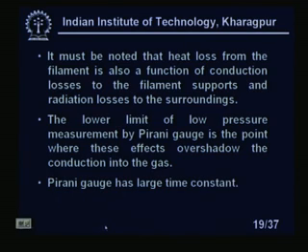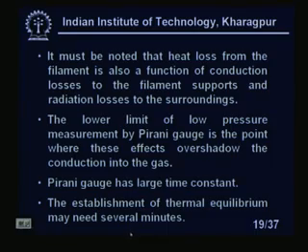Now, one of the greatest drawbacks of the Pirani gauge is that it has a large time constant; the measurement is not immediate. The establishment of the thermal equilibrium may need several minutes, because it is a thermal system, so it may take several minutes before it settles down.